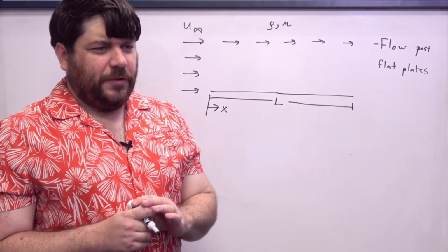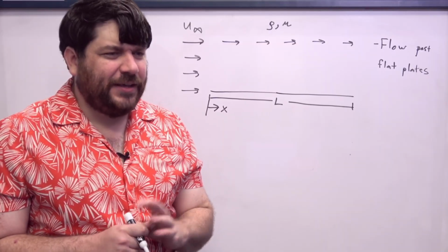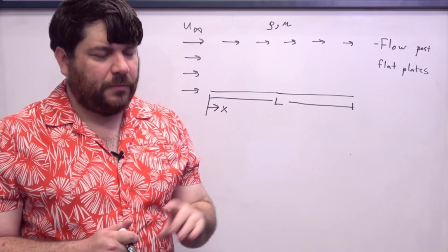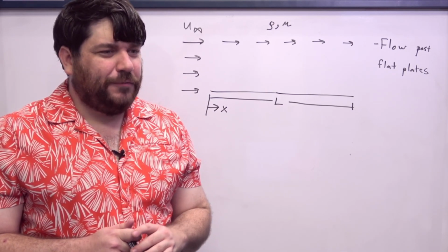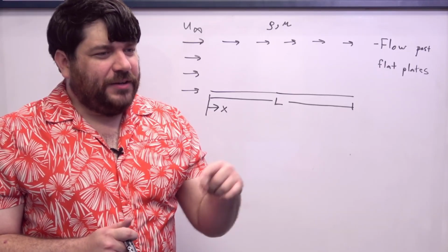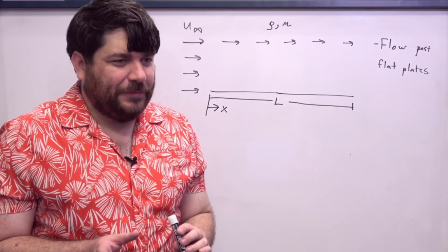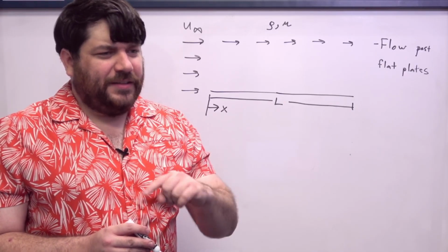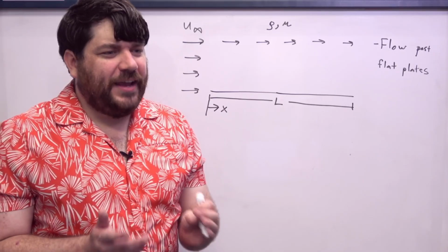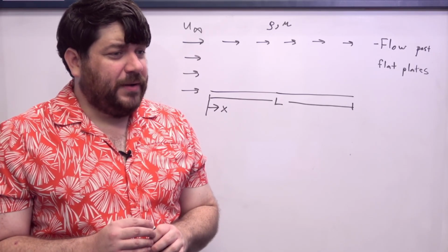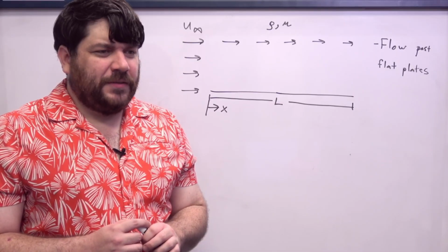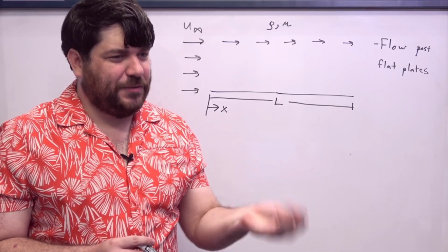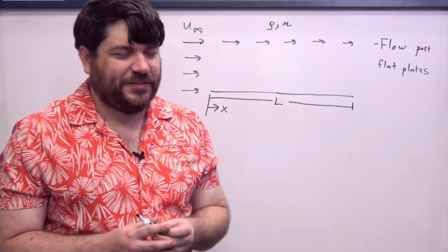And so the goal of what we want to do when it comes to convection isn't necessarily to understand how heat transfer happens inside of a liquid. What we want to do is see if we can use the relationships that we've developed already to model heat transfer that happens between a solid and a liquid, and then see if we can find expressions for H that are derived from experiment or empirical correlation, and how those relationships are connected to the geometric and material properties of the objects that we want to study.